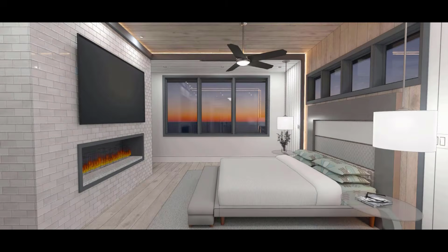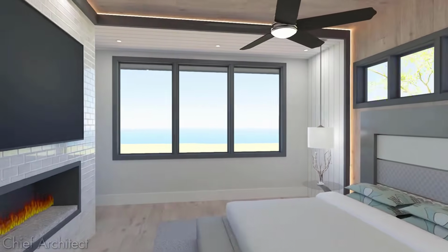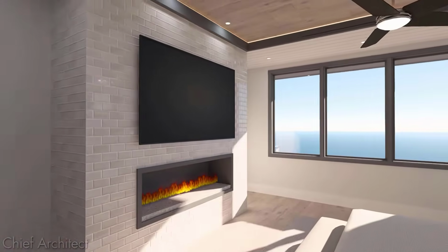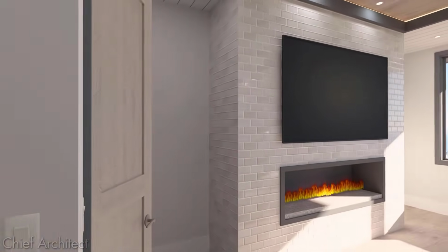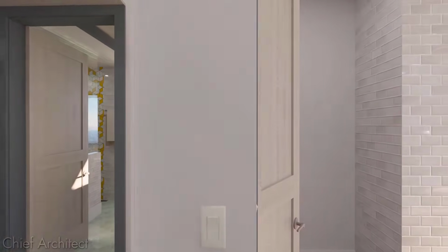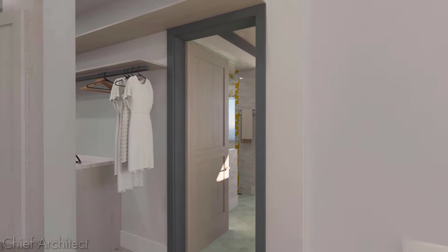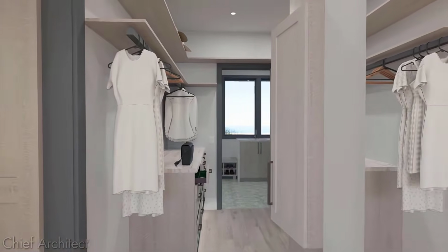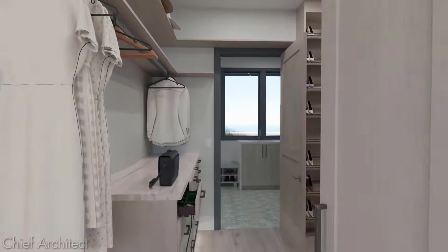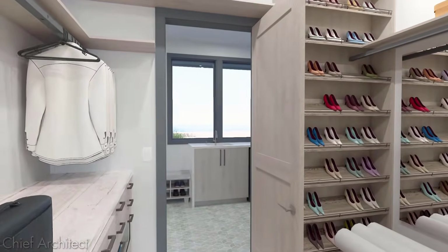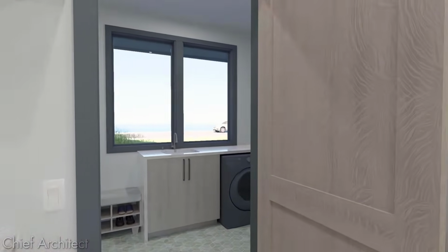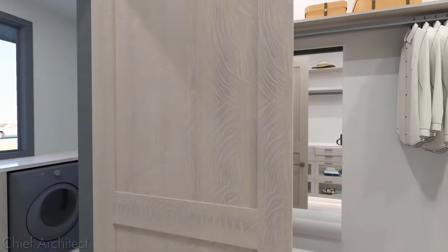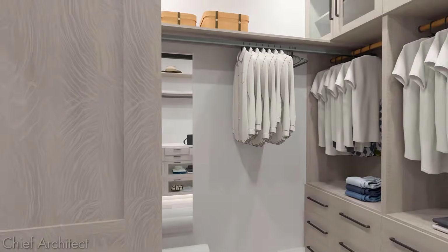When you create a walkthrough path, and let's say you have a whole house, one of the things that I do is use small walkthrough paths and stitch them together with an external video software. I try to avoid having one large walkthrough path. They're time consuming to record, and also if you find you need to make edits to it, it can just be time consuming. So I usually create small walkthrough paths. You see I have a bathroom, a closet. I will create a walkthrough video outside of Chief Architect by stitching those together.